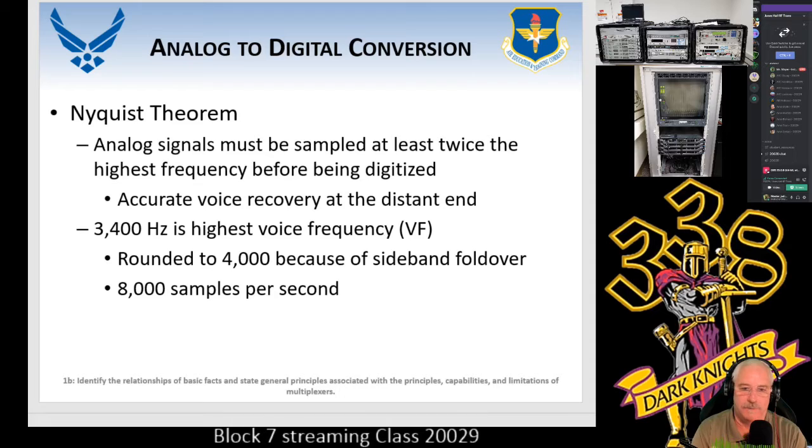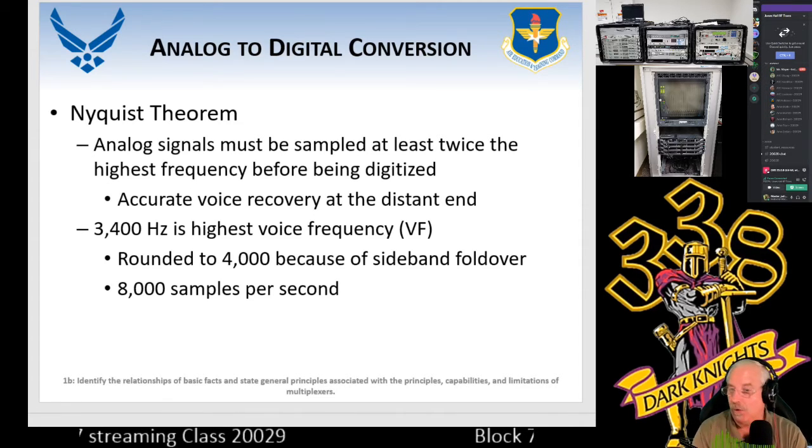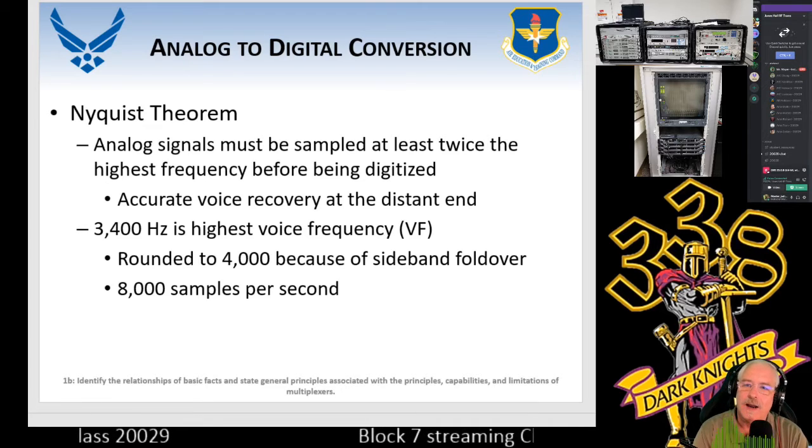That audio program is probably one of the best freeware I have ever seen in a very long time. They're getting really good at it. Now, the reason why I brought up Audacity is there's a place in there when you get ready to save your audio as an MP3, you have some selections there. Everything from 8K, and that's a sample rate, all the way up to 320K. It is insane how they work that. So when you take a look at PCM, we don't need to be at 320K. We only need to be at 8K. Why? We're only doing voice.